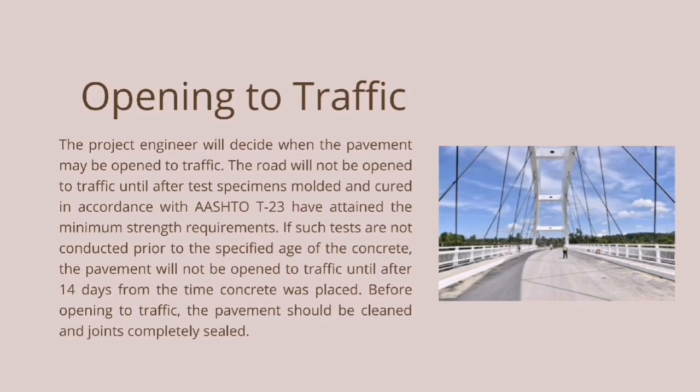If such tests are not conducted prior to the specified age of the concrete, the pavement will not be open to traffic until after 14 days from the time concrete was placed. Before opening to traffic, the pavement should be cleaned and joints completely sealed.